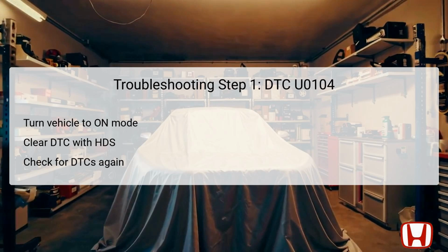The first troubleshooting step for DTC U0104 involves verifying the problem. Begin by turning the vehicle to the on mode without starting the engine. This allows systems to initialize and become ready for diagnostics. Next, clear the DTC using the Honda Diagnostic System (HDS), a tool specifically designed for vehicle diagnostics. This action resets any stored fault codes.